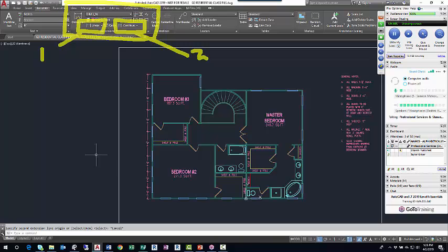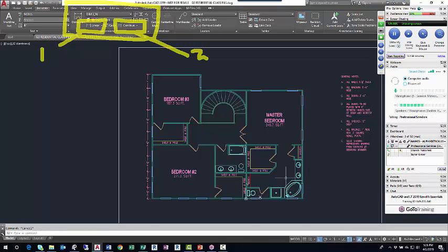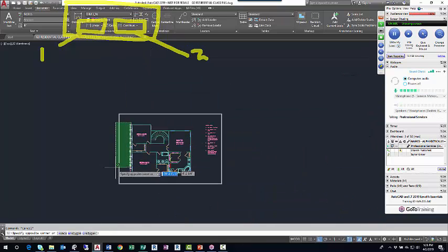How do you get it to stop at the midpoint? Make sure you have your midpoint object snap on. See if that's on. Sort of bring up that. Midpoint object snap is on. Okay. So was it on before? Yeah. Okay. So let me erase some stuff here.